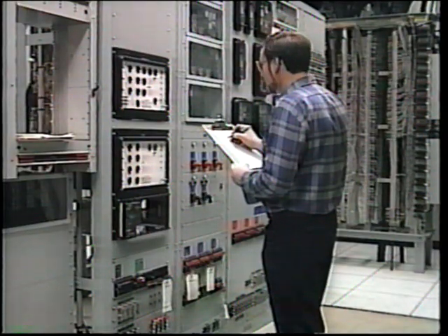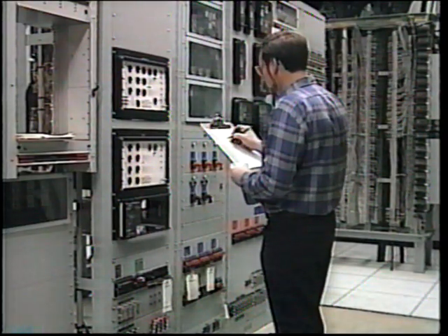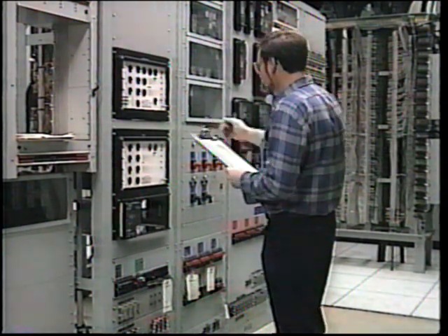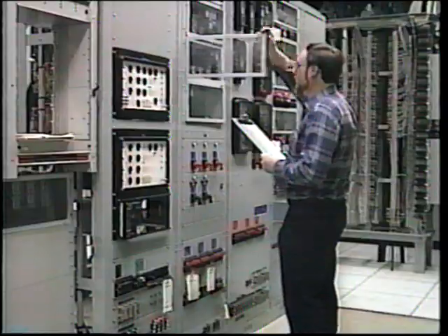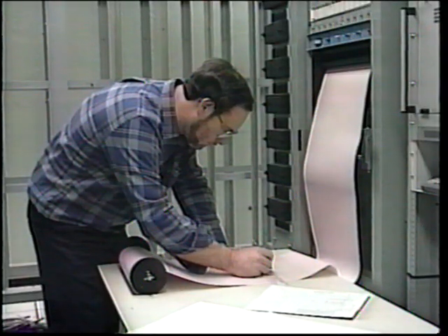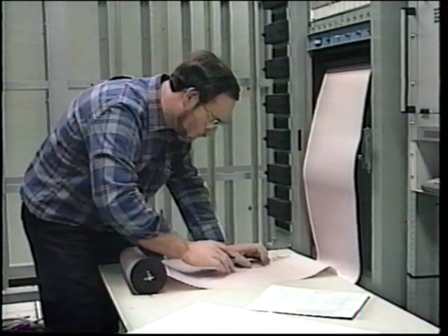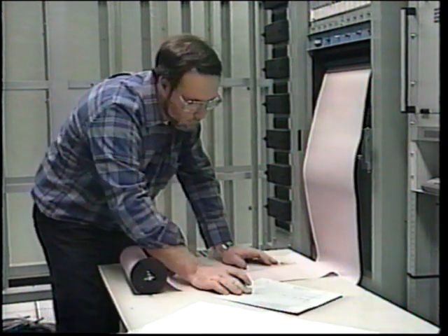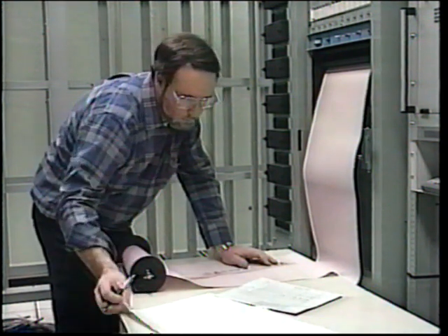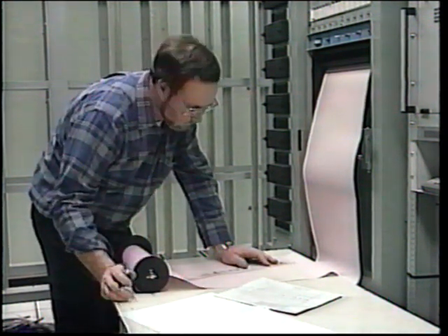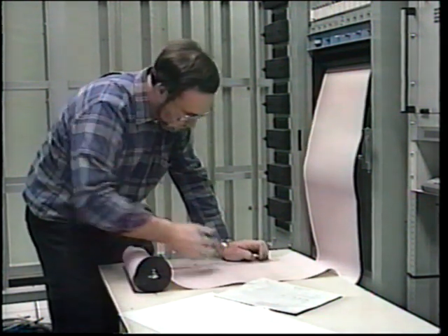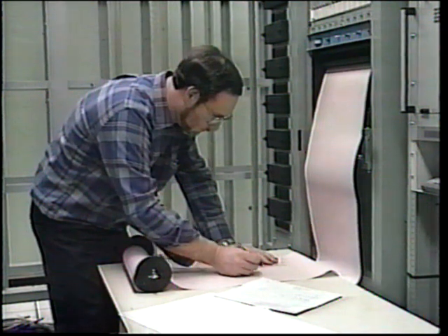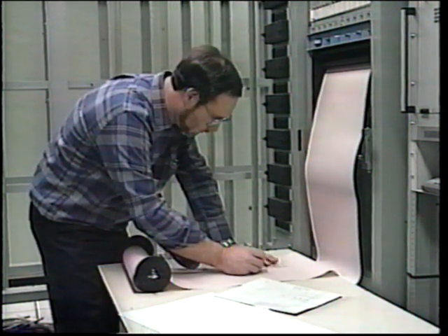Another tool we need to use in fault investigation is information regarding relay targets, which is usually logged by operators. Like the SER output, these logs are normally used to verify and support the conclusions drawn by examining the oscillograph records. However, in some cases, relay target and SER data have provided the missing link in solving problems due to disturbances.